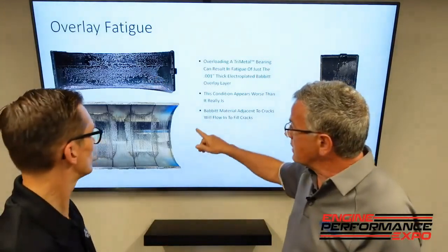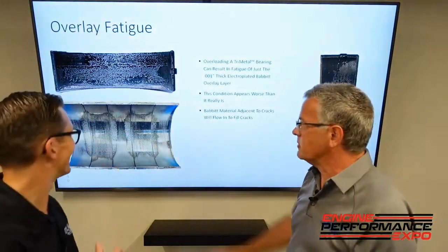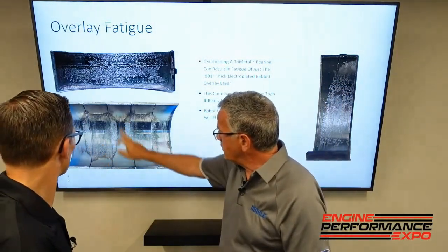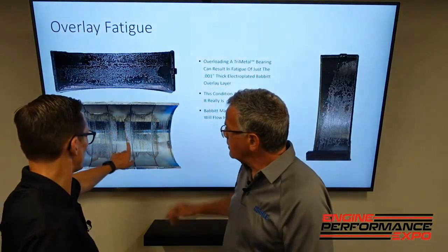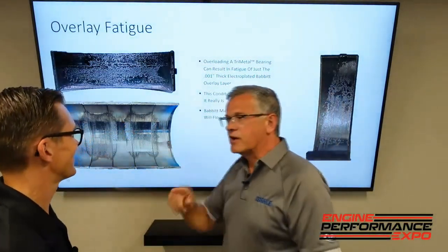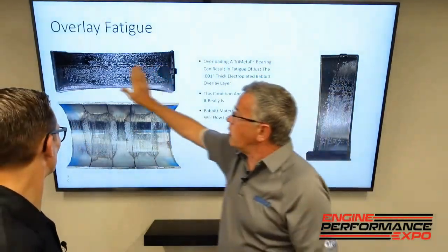The interesting thing, this set right here, if you look. Ooh, yeah, there's two things going on here. A lot of fatigue going on here, but if you look at how these are elliptical shaped, concentrated right here, and it's clear in the middle. On the ends, crankshaft flex. So you're fatiguing in a part of the bearing, but not the whole bearing.